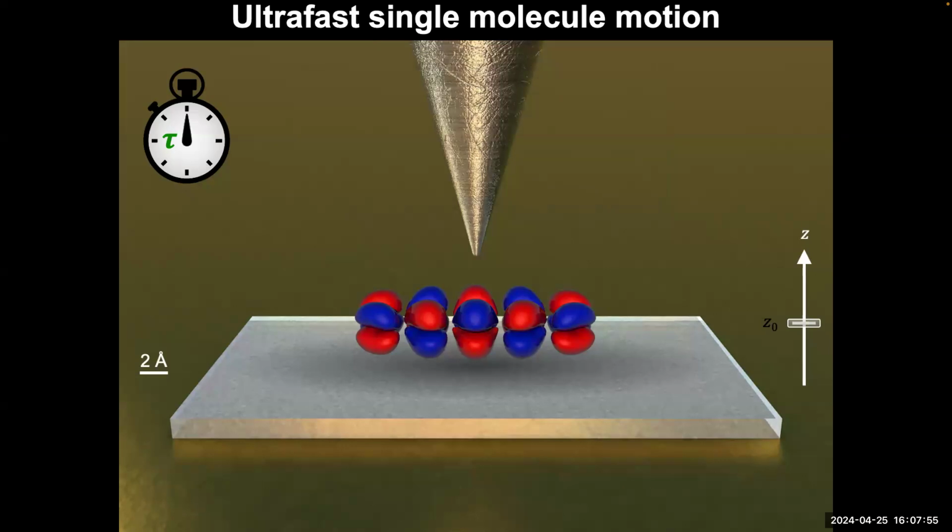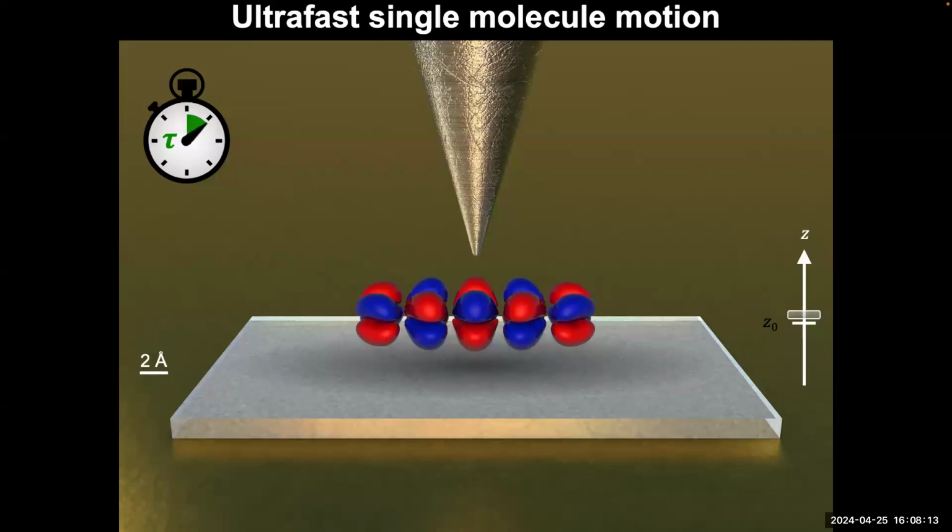We're going to charge the molecule, and then it's going to take some time to recover, and we won't be able to take electrons out until it's recovered. That's not what happened. So what actually happened was we took an electron, and this thing was very quickly neutralized by the substrate. But because of this tunneling event, the temporary charging gets kicked. And so it kicked and started moving up and down the junction.